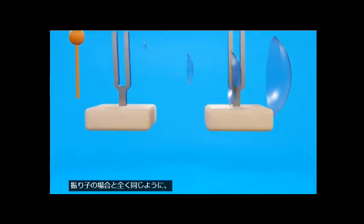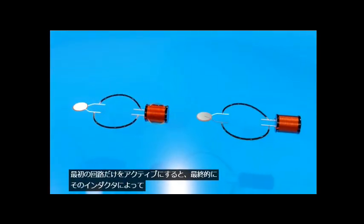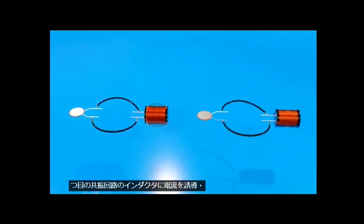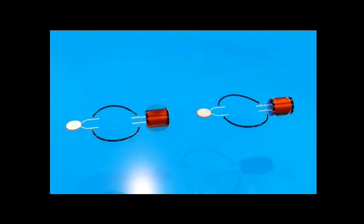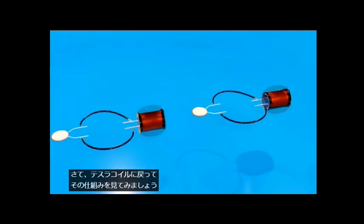So thanks to this behavior, if we position two resonant circuits, but only the first one is active, eventually electromagnetic waves generated by its inductor will begin to induce and amplify a current in the inductor of the second resonant circuit, enabling power transmission wirelessly over much greater distances. Having taken all of this out of the way, now we are able to go back to our Tesla coil to see how it works.